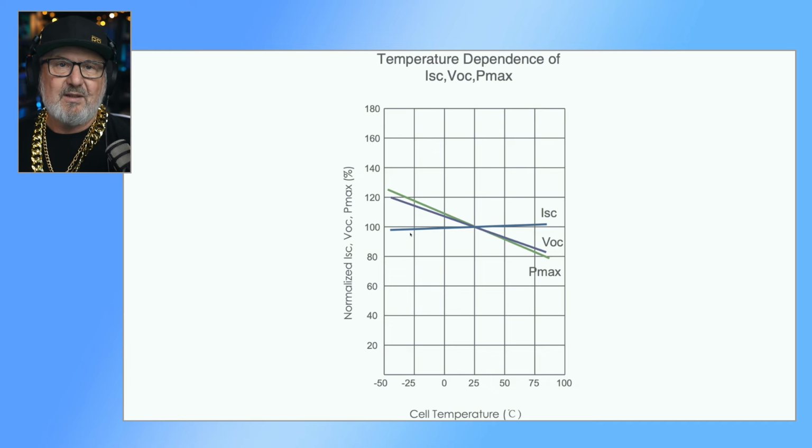with air temperature. So a PV cell has a similar thermal rise characteristic to metal. So you put a tin roof in the sun and it's a 20-degree day, that tin roof will not be 20 degrees. It'll be way hotter. So the specific heat value of the metal means that it will gain heat quite significantly from ambient. And the same is true of a solar cell. It'll be a lot warmer, typically 25 to 35 degrees hotter in full sun than the ambient temperature. So we always talk about cell temperature when we're referencing any of these characteristics, voltage, current, or power.